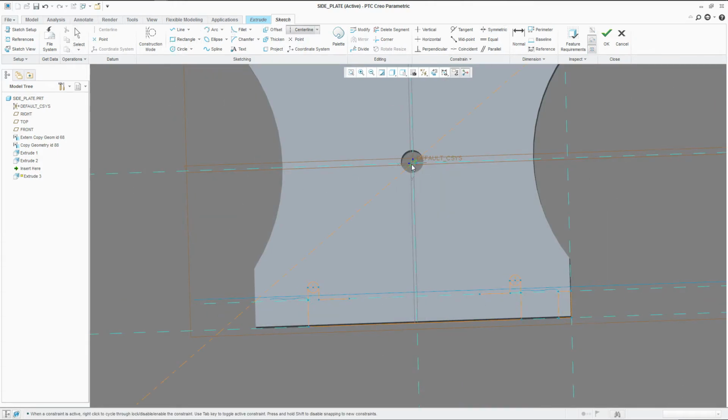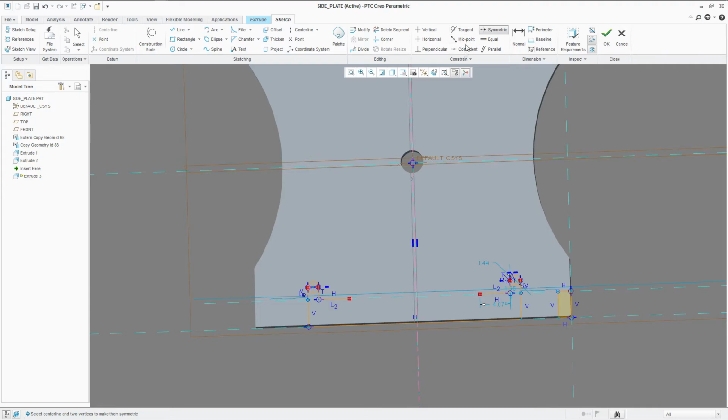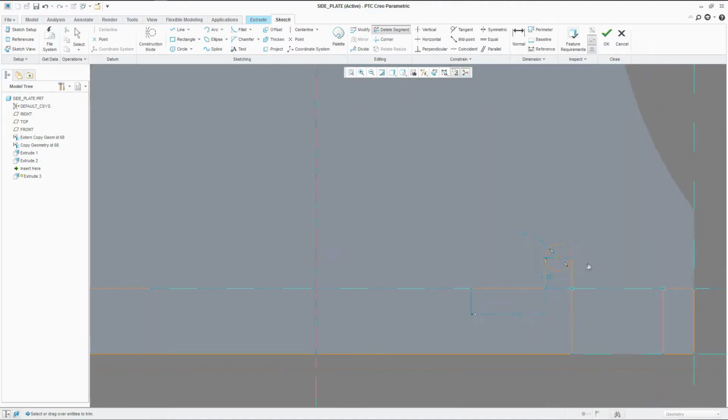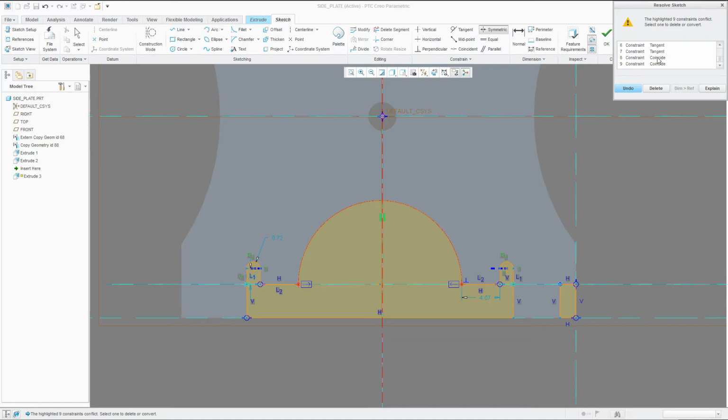Let's place a center line for symmetry. Right. Now let's remove those segments here. And we still have to close this one, and we're going to do this with an arc. Go out of the top and make something like this as you like, and let's place this one nice in the center.